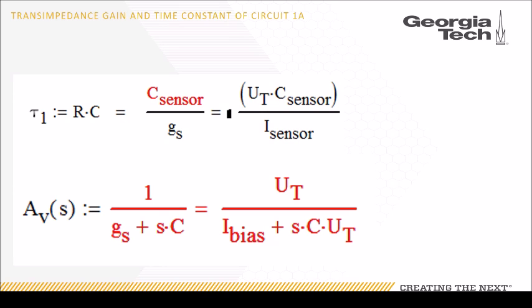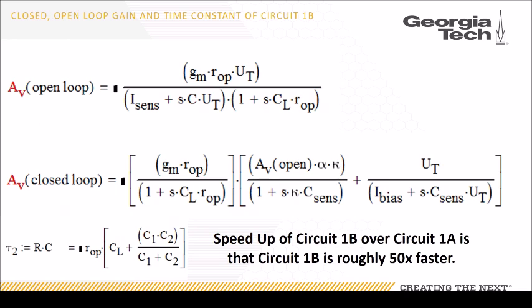And again, for the gain of the first circuit, you have the thermal voltage over an I_bias term plus an s times capacitance, which is a pole. And as a logarithmic, coming from the logarithmic response of the DC, the term you see in there is a thermal voltage, which comes from that expression as well, and that contributes to the gain.